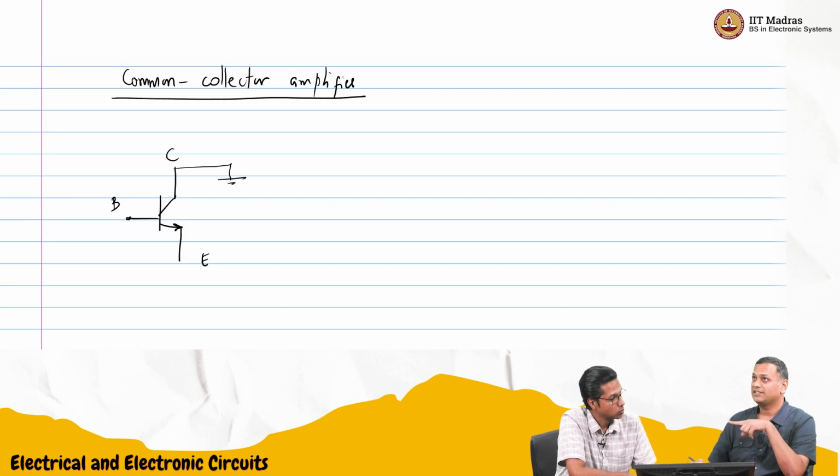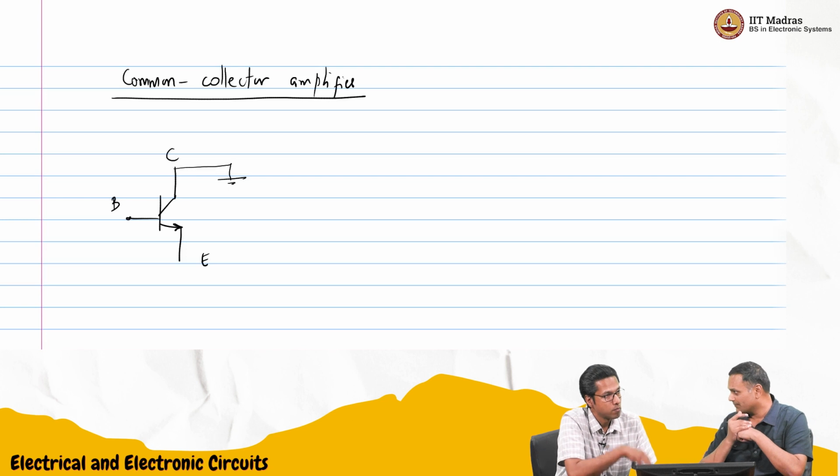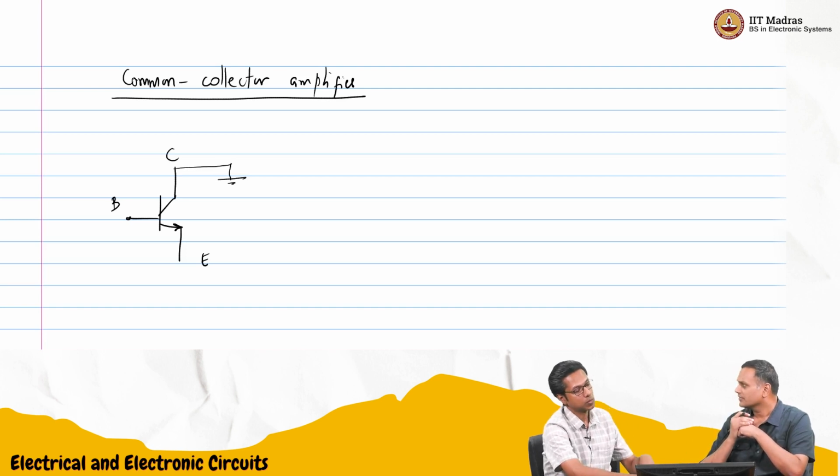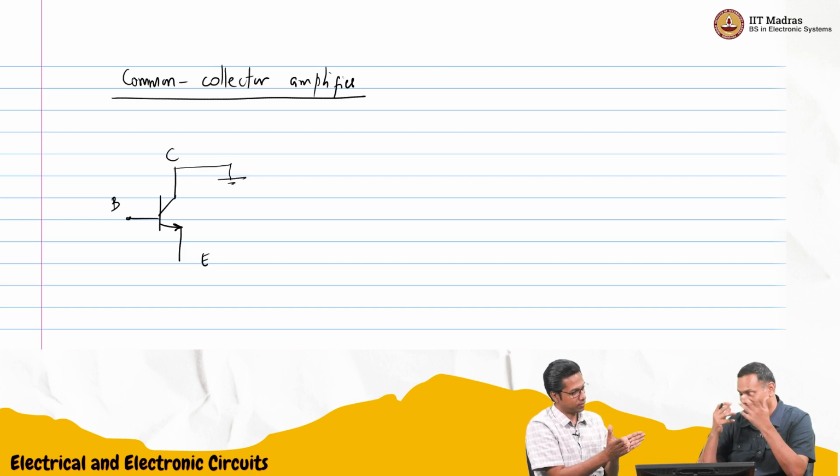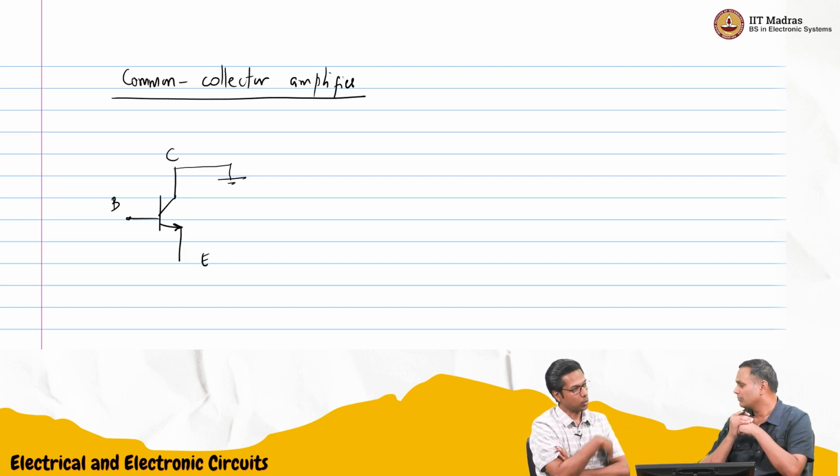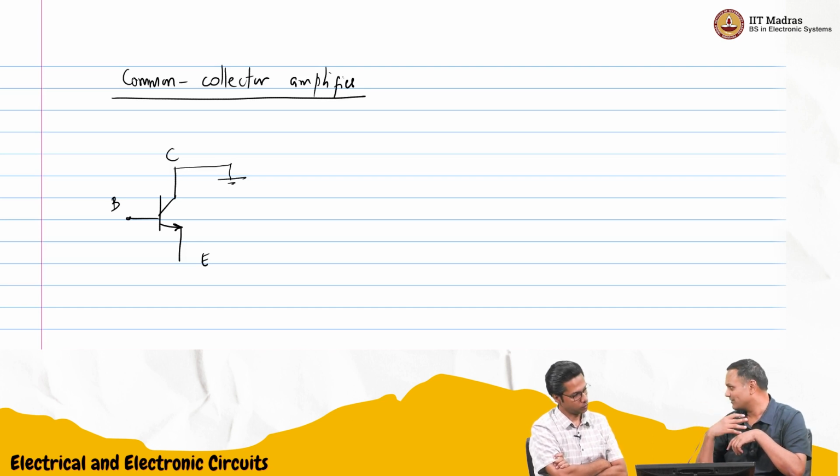Well, the transistor is basically amplifying the current, no? So IC is beta times IB. So in some sense it is a current amplifier. So somehow it seems to me that the base should be connected to the input signal and collector-emitter should be the output. Somehow the base-emitter has to see the signal. Only then the exponential effect can be utilized, and that will cause the collector current to be some large ratio with the base current and so on.